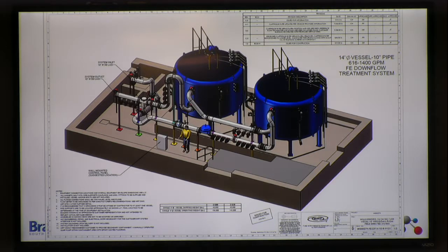And it's also a sizing issue. So if you put it there, then you have to decide, well, how much water are you going to put through there? Because there's a certain area, your experience in engineering said these have a loading rate associated with it. So if you do that, do you size it for well 6 plus well 7? And treat all of your water with radionuclides? So there's an optimization in design.